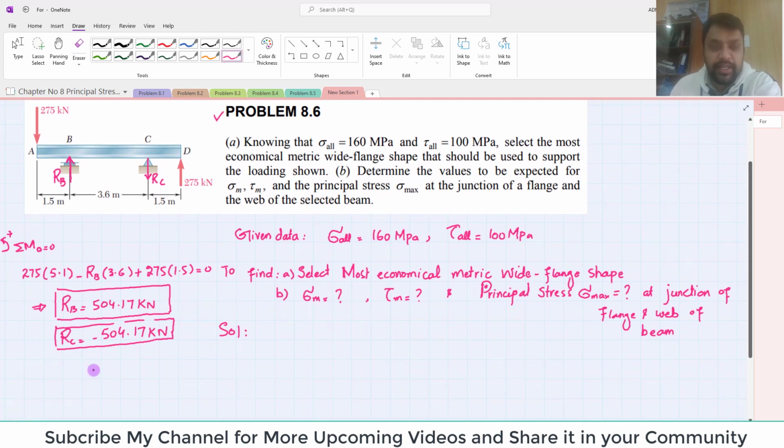Now the next step, in order to find the most economical beam, is to find the section modulus, because you know that maximum stress is equal to maximum bending moment divided by section modulus. We can also write it as: allowable stress is equal to maximum bending moment divided by the minimum section modulus that should bear the allowable stresses. So here you will have to find the maximum bending moment for the beam.